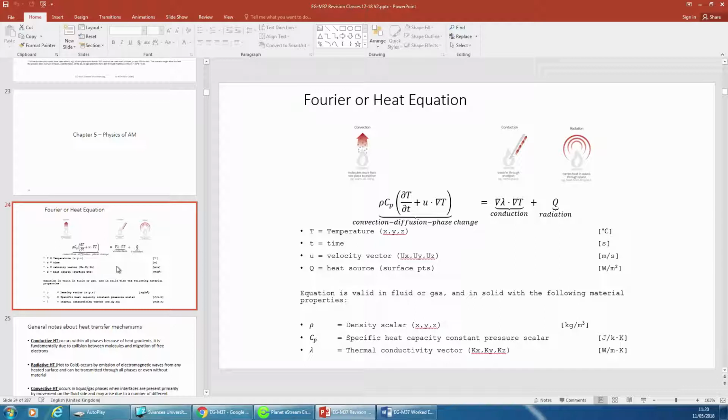CO2 lasers on the one end, where you've got a larger wavelength of laser, are used more typically in the powder deposition, and then on the powder bed, we're using more the 1 micron wavelength lasers, and ytterbium fiber optic lasers are typical of all of the powder bed processes now. But they have been through iterations where they've used different types of lasers. It's just that the ytterbium fiber optic laser is the most efficient in terms of the energy use.